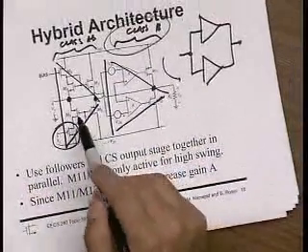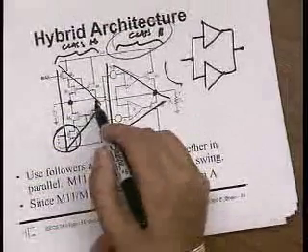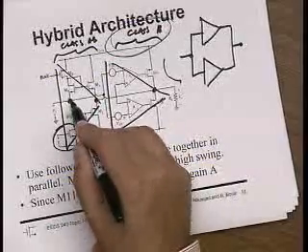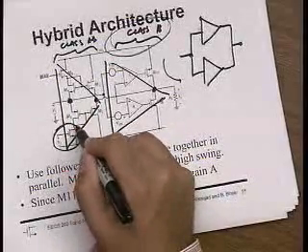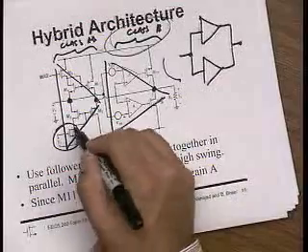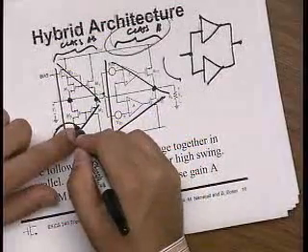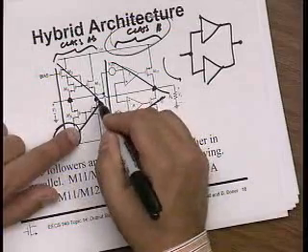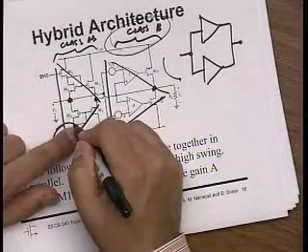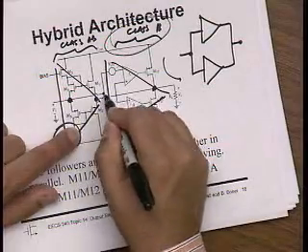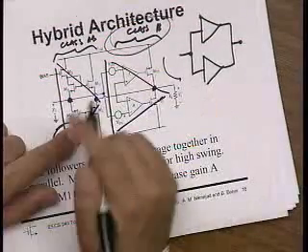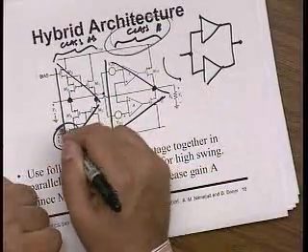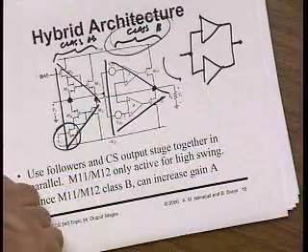So you take this input here. The way it's been drawn here, this input is the same as this input, right? Because this is just a follower stage. So this is the input signal at this point, a voltage here. If I move this voltage around, this voltage also follows. This voltage is just a level shifted version of this voltage, and I use that to drive the stage. So it's just one input voltage coming in. And here, as drawn, it's using this transconductor to produce that voltage.